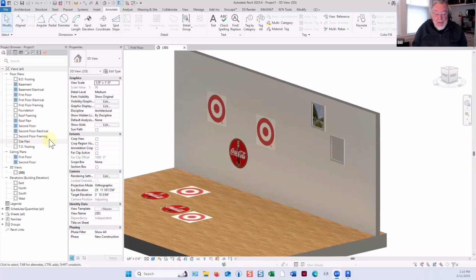Load it into the project and apply the Pioneer stereo receiver image that I just emailed you guys as a decal to its face. We might need to crop or otherwise reshape the image into a true rectangle in Photoshop with edit, transform, skew, or its cousins. And then the final proportions of the decal can be set in its properties in Revit, so it'll fit, centered and everything on the receiver.